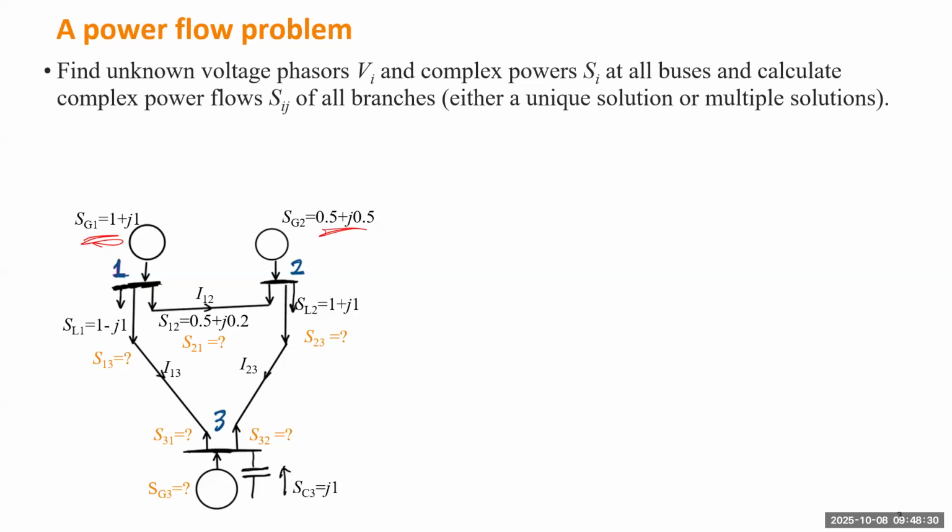So for this one, that indicates a capacitor. A capacitor is a reactive source. So the final calculation will tell us, by using the base, that this one provides 100 megavar reactive power. So for this question, we want to calculate the line flows of complex power.